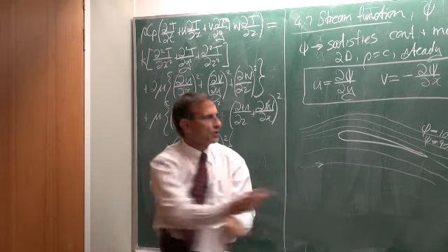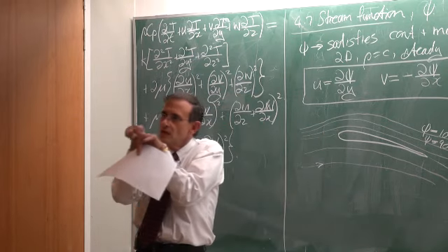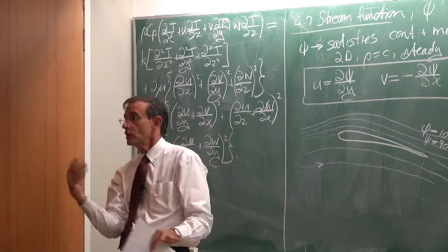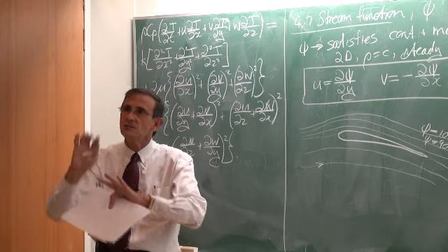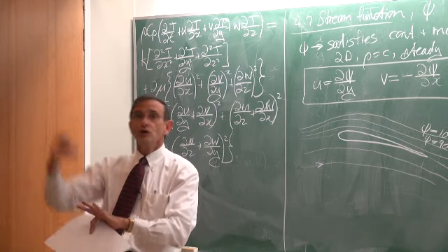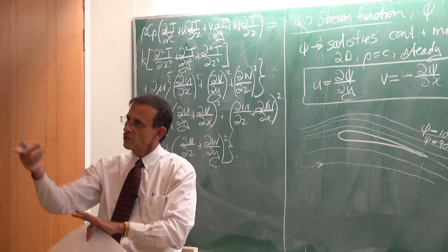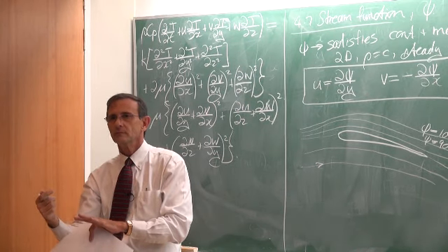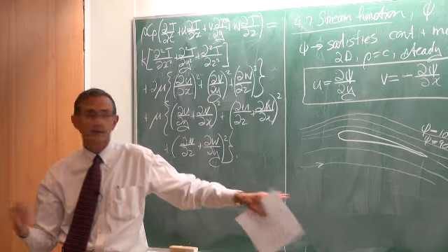If the lines start going closer to each other, then the velocity would increase between the lines. Right. So just by looking at the flow field, you can already see where the high velocities will be and where the low velocities will be. The moment you know that, you know what the pressures will be, because that would just be the opposite. If the velocities are high, the pressures would be low. Very, very important for the design of an aeroplane wing.